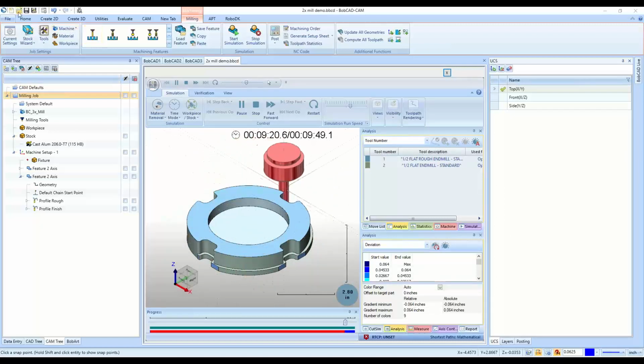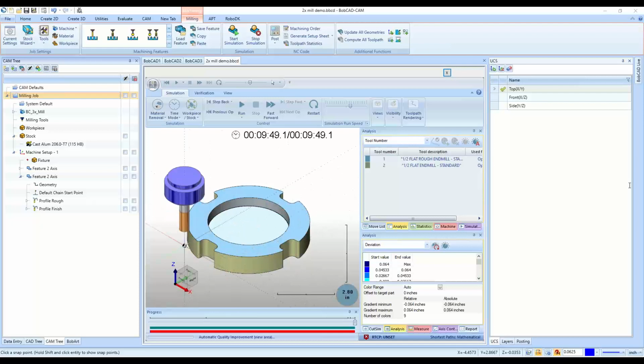Now under the Create 2D tab and then going to line, you're able to click one point and click on another. And I think the most efficient, at least getting started with drawing, would be you can set your start point in X and Y coordinates. So if you want to start at X0, Y0, you just type those numbers in. And then under absolute, you can type in the absolute coordinates where you want that line to end. Anyways, I'll get out of the chat here.